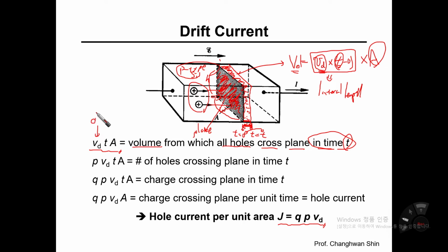Again, Vd indicates the drift velocity. Notice that an electric field has been applied, which means a voltage difference exists between, say, location A and location B. The voltage difference between A and B is V, resulting in an electric field between plane A and B. Under the electric field, we have learned that a force is applied to all the charged particles in the p-type silicon material.